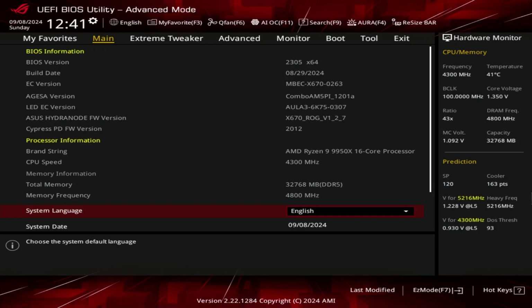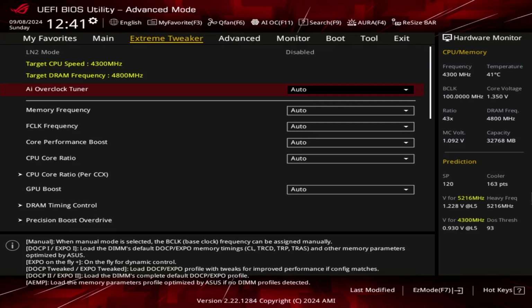I find that the easiest way to approach Curve Optimizer is by first finding the weak part of the curve, and that can change architecture to architecture and chip to chip. I found that in this case, the Y-Cruncher BKT workload was the first one to become unstable when I was doing curve optimization. Upon entering the BIOS, go to the Extreme Tweaker menu.